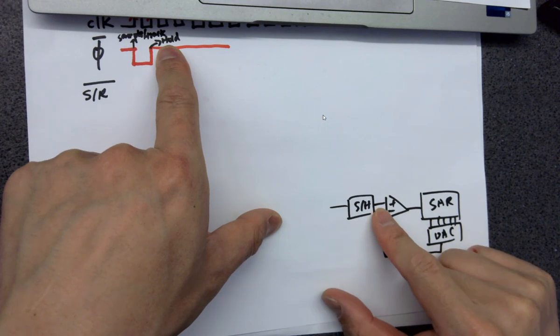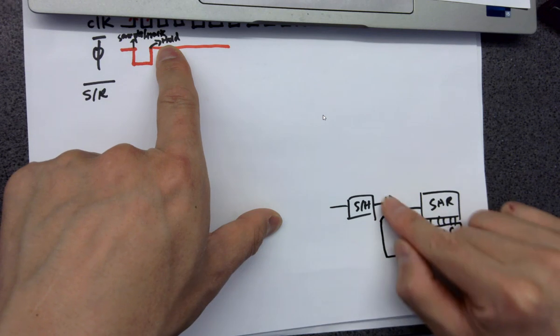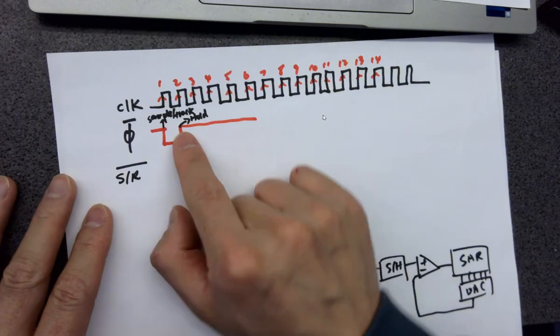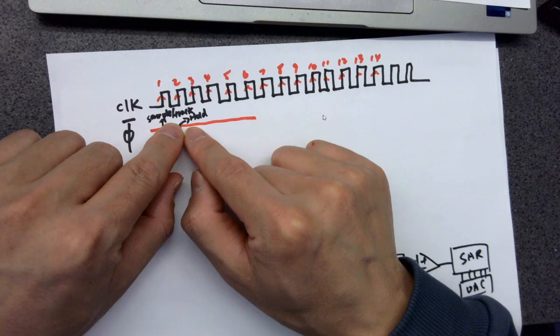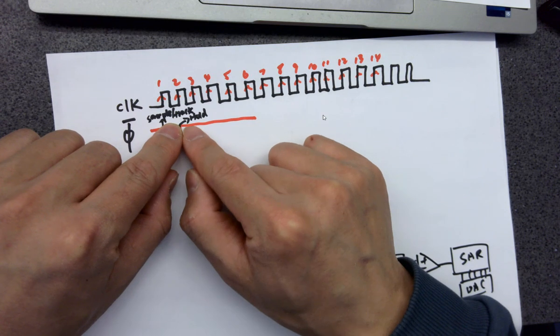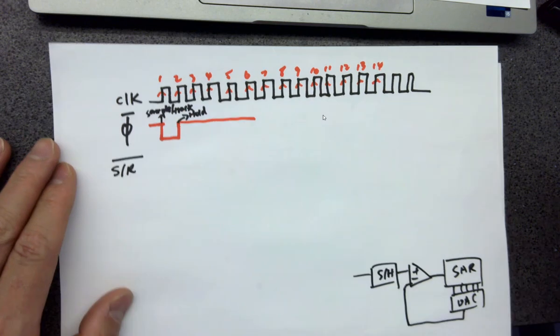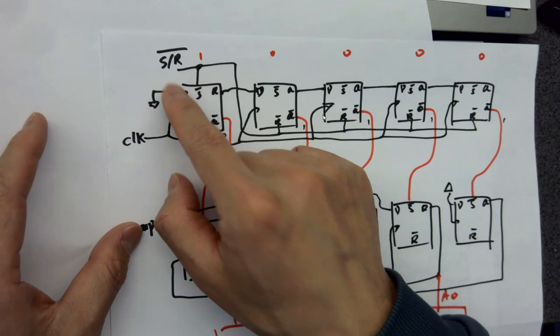So whenever the voltage appears here, it starts doing the conversion. It's comparing, right? Nothing can control it. That is why you need this one to be held here first, so you get a good voltage value, the voltage value you want to convert. Hold it first, and then make a dip here to start a conversion.